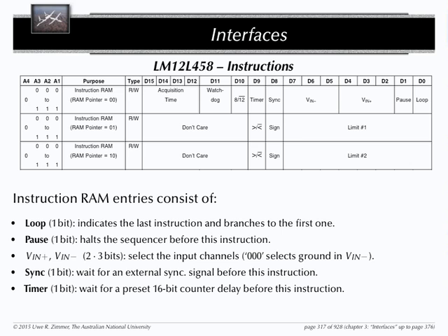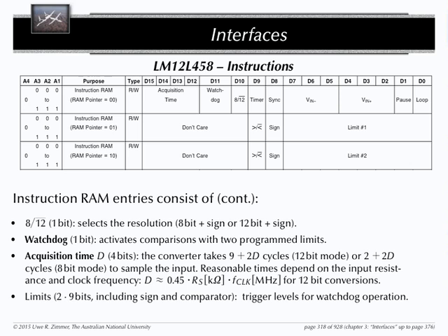What other instructions do we have in there? Then we have to select the conversion resolution. We have to set whether this is an 8-bit or a 12-bit conversion. Watchdog activates comparisons with two programmed limits. What could that mean?